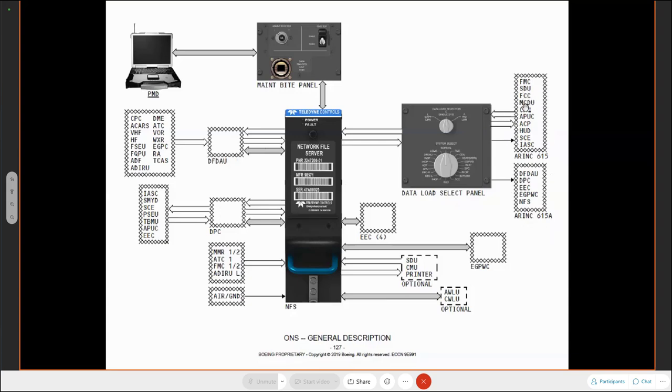For these components, as you can see here, the flight management computers, the satellite data unit, that type of thing, head-up display if you have it, the audio control panels, APUC, integrated air systems controllers. Again, this information goes through the data load panel, okay? Not only does it arm the system to allow them to accept new software, but in those cases, the software is going that way. Okay, so this is allowing existing systems on the NG to basically interface with this box. Some interface directly, some indirectly, okay? So all your software, majority of your software is going to be stored in this box as well.